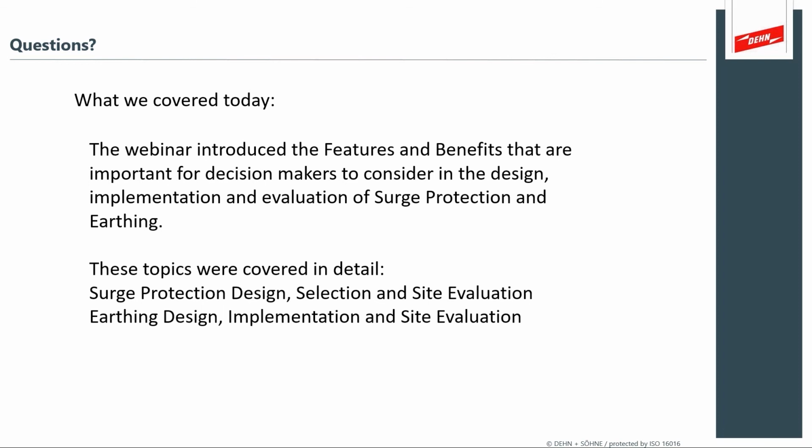Excellent. I'm going to ask you, I just want to find something that is really relevant. As per the questions you mentioned for selecting power SPDs, we need to match the SPD kA rating with the corresponding circuit breaker kA rating, or with the bus short circuit rating. So it's the SCR rating, the abnormal short circuit current rating of the breaker that's upstream. So the SPD needs to be higher or equal to the breaker that it looks upstream at.